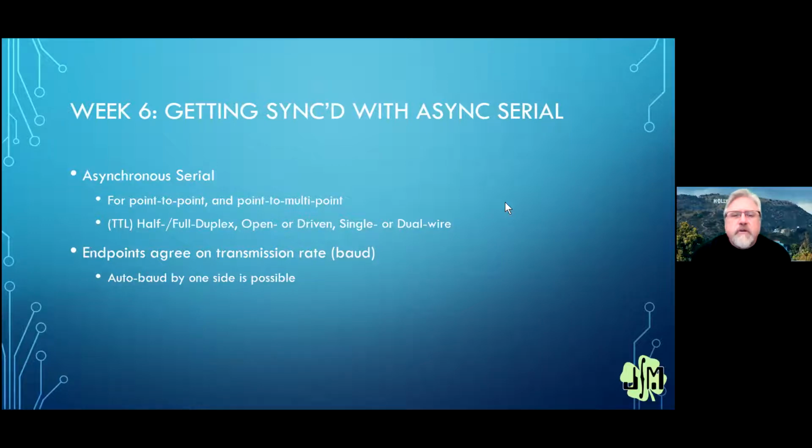We're going to see, as we're looking at the construction of serial data, we have more than just the data bits in each byte of the packet. We have what's called a start bit, which says, hey, here we come. And then we have a resting period at the end of the data bits called a stop bit, which could be more than one stop bit.